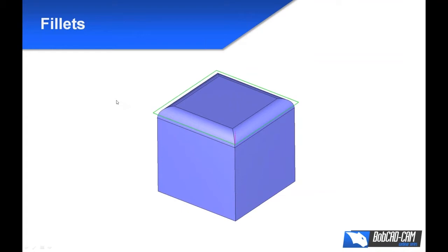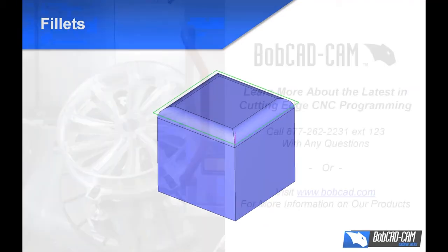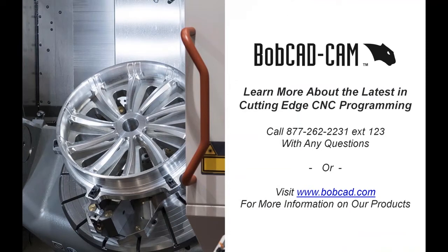And filleting. I mean, you have two different options for filleting, okay? Normally, if you have a corner round tool that's big enough to create your fillet, great. You can use the corner round tool and use that in the 2-axis. Now, if you don't, you need to use a ball mill and step down. There's a couple ways you can do it. So we'll go over a couple different toolpaths to cover getting those fillets. And then that'll pretty much cover everything that we're going to cover today.